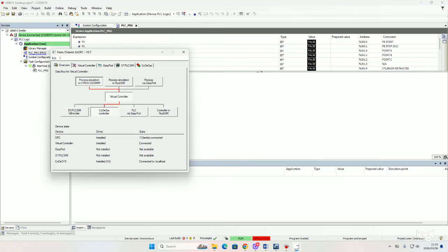Usually if you have an S7 PLC SIM controller by default, there you go, it's disconnected, execution suspended, one client is connected, which is correct. So usually you'll get your Easy OPC connected to the S7 PLC SIM controller by default, right? So you have to change that and click Codesys controller because you have your CIROS connected virtually to your Codesys.